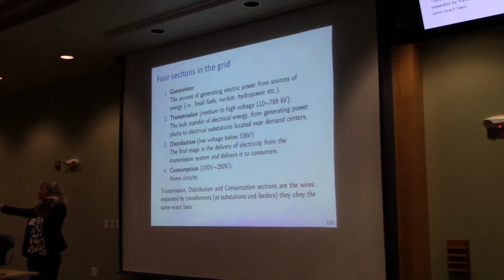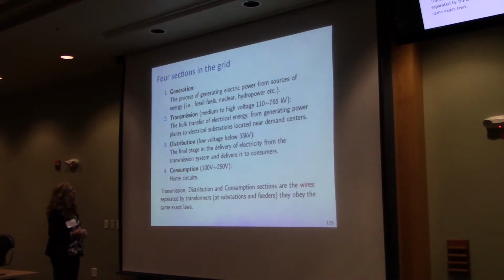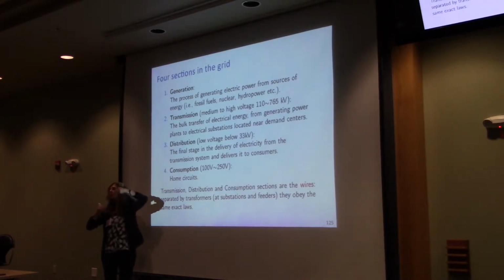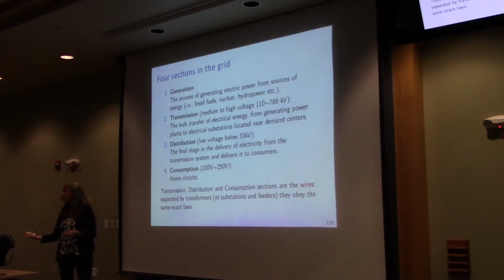So usually the distribution feeders operate like a tree, sprinkling down the power to the different consumption points, while the transmission network is this mesh, which is kind of a pool where you try to get power from different points where the bulk generation resides. And so far, the generation typically goes from the core to the edges. You don't get power from the distribution network upward. Even though there is today a lot of renewable power, which is solar PV rooftop, and if that becomes excessive, you will have to ship power from one substation to another one.